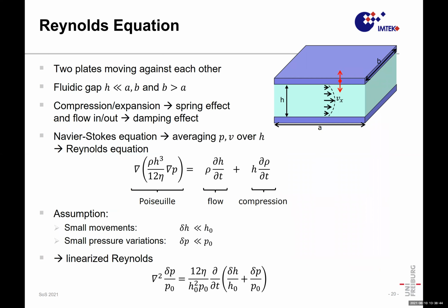Then we use the so-called Reynolds equation if we want to solve the situation that the flow is not generated by a pressure gradient across a plate, but by, so to say, squeezing the plate up and down on this air cushion. So if you have a parallel plate displacement, of course, the air has to go in and out of this situation. And this is described with this Reynolds equation. So we have somehow a plate A times B and a movement out of this effect.